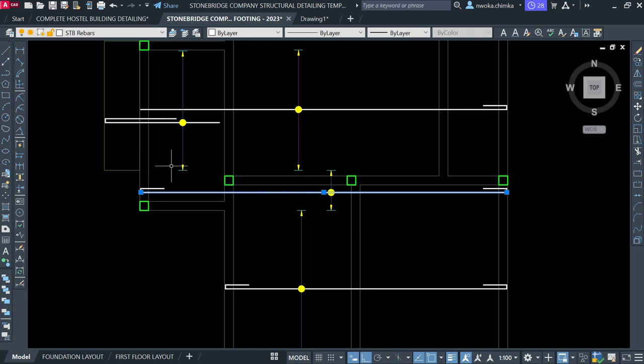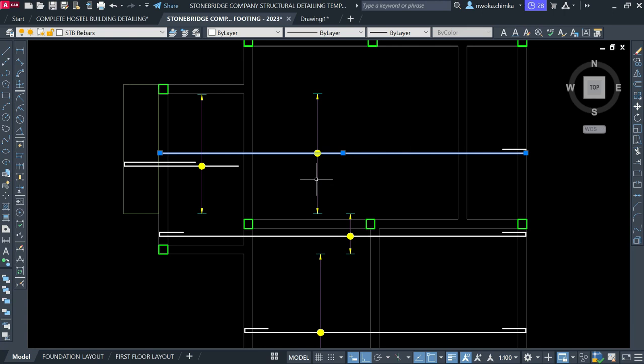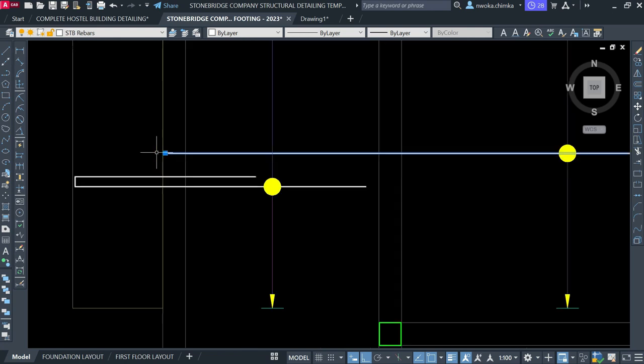So when this bar comes to this place, it finds that there's a cantilever that spans from this point to this point. So it now has to stop here. It has to stop at this place. So when it stops here, this very one picks it up and continues from this place to this very place. Now, this bar is running, trying to bend from here.